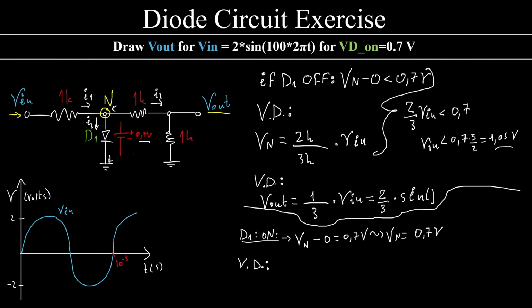I'm going to erase this for now, and I'm going to notice again that I also have a voltage divider. But we must be very careful. We cannot take a voltage divider with this V in all the way to the ground. Why? Because this current that we have found before, I1, is splitting into something over here and over here, and this is not a quantifiable resistance.